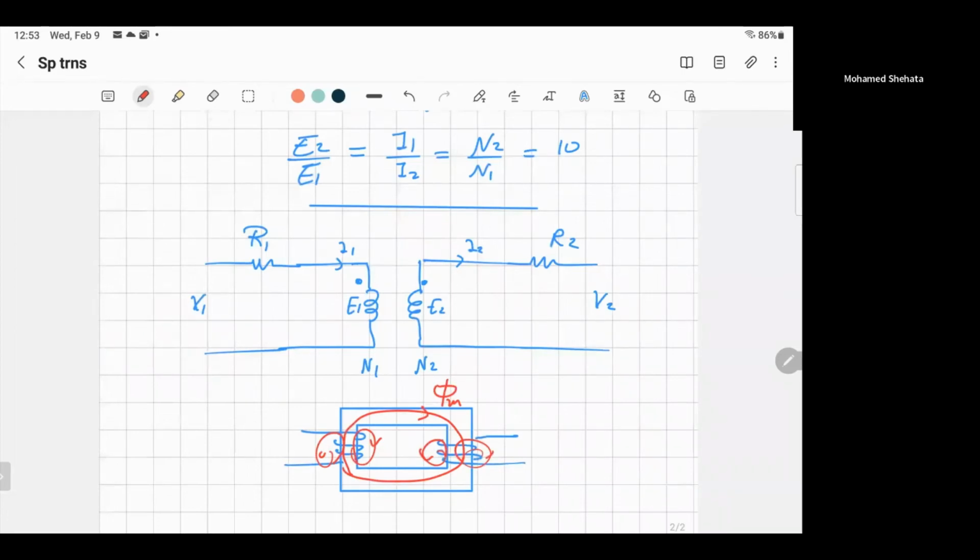But the one that we use to calculate the induced voltage, I'm going to account for it. No. Loss. There's loss in the magnetic field too. How do I represent it? Well, we represent it by a reactance or inductor. Because of leakage, we call it XL, and the corresponding inductance, we call it LL.